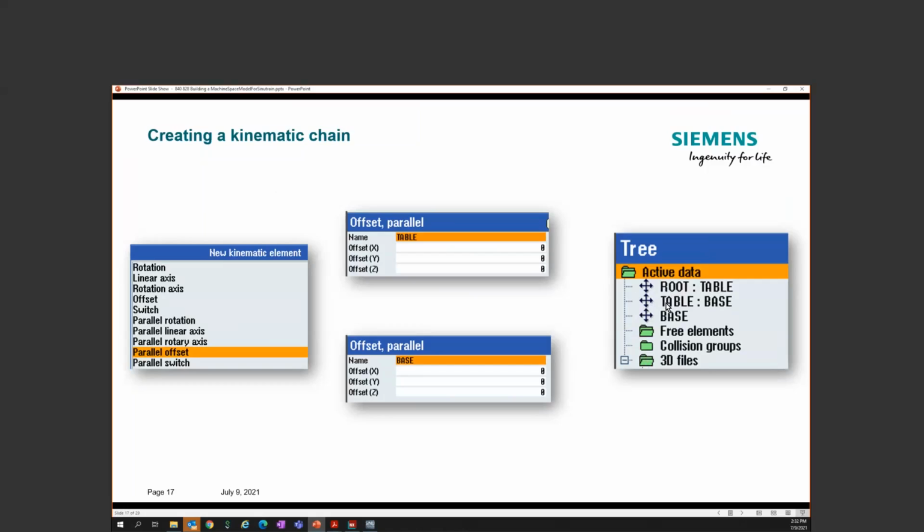Then I'm going to have the table. My table is completely separate to the spindle, right? In this case, it's not like my table's fixed or anything. So I will have a whole extra series of offsets driven under this table. And then the last one's going to be my base. That's going to be something for me to display my frame offsets. So let's get these first couple offsets set up.